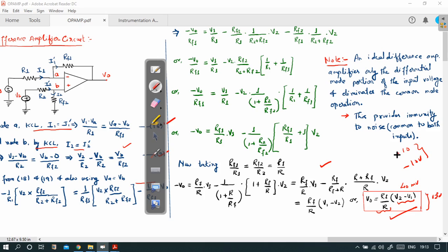then there is a question whether you can get a 12 volt signal from this op-amp output when the power supplies are given as 10 volt. It will not work in this case, and you will get a value at the output equal to 10 volt and not 12 volt. If you get any value higher than 10 volt, you can get a maximum of plus 10 volt at the output. Remember this, and use it when you are designing or working with op-amp circuits. So there is a limitation.